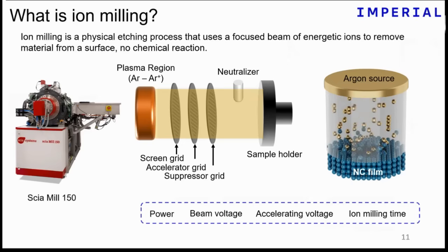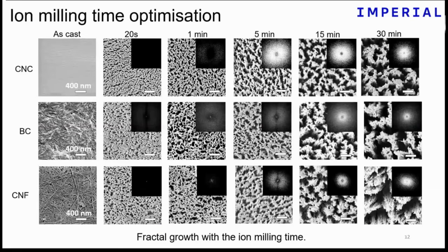One of the methods that we use is a method that kind of blows the surface up, it etches the surface with some kind of ionized gas. It doesn't matter which one it is. In this case, it was argon. You apply a voltage, these ions bombard the surface, and they will destroy the surface, but not arbitrarily. So, an example of what it does.